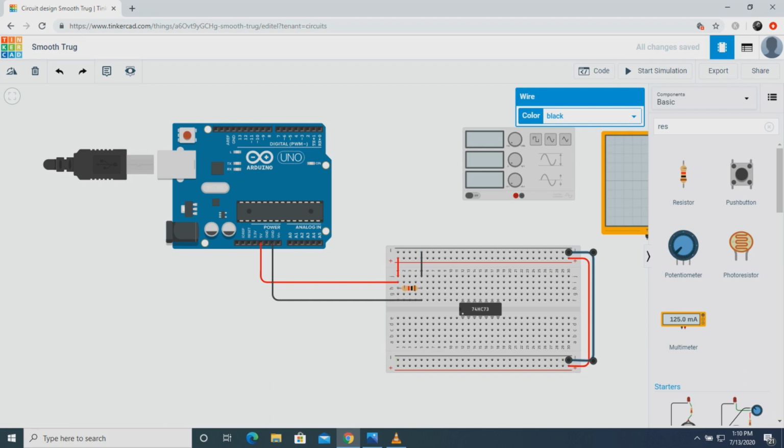Now I need to give the power. You see that the middle position, pin number 4, is the power, so it should be served with the VCC. This is my VCC rail, right? So simply, you drag this thing to this node and make it red, so the power has been served. Similarly here the ground, so connect this to this and make it black. So now the IC has been served with the power, right?